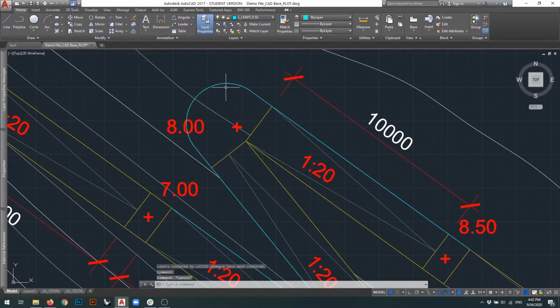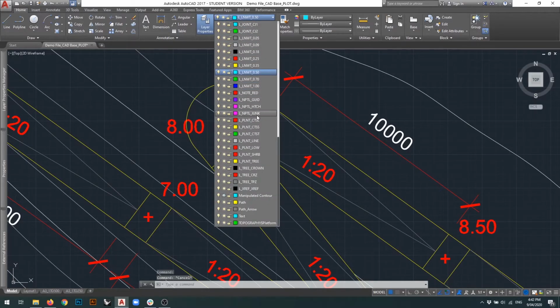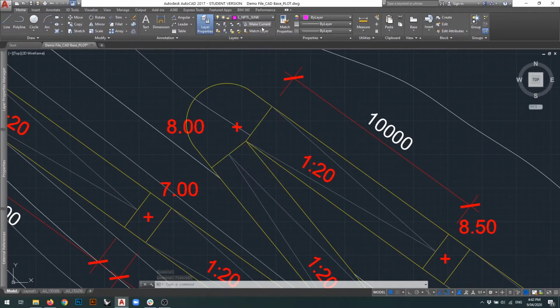So what we can do is further divide this particular arc into 4 different sections. So 1, 2, 3, 4. So we find the center point of this half arc and center point of this half arc. So again, we use the previous method by drawing some guidelines.